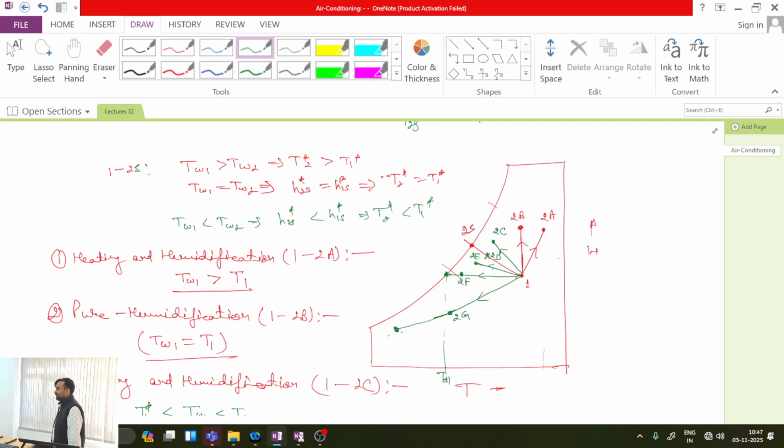And nowadays, even if you have a water body available close to the power plant, you still have to use a cooling tower, because whenever you dump the hot water into the water body, it creates thermal pollution. Because of thermal pollution, the water body temperature will increase, so whatever species are present in that water body will be dying down. Is this point clear? So the purpose of the cooling tower is clear.